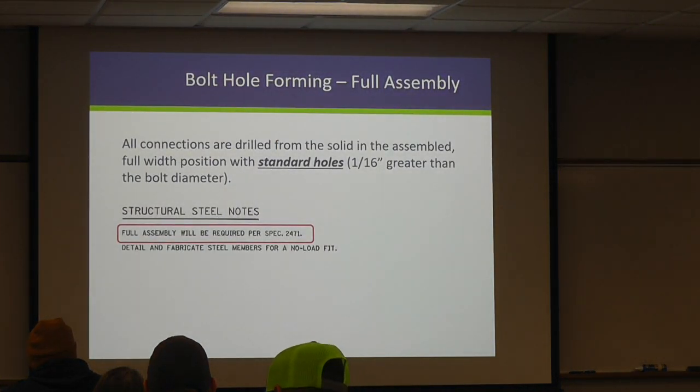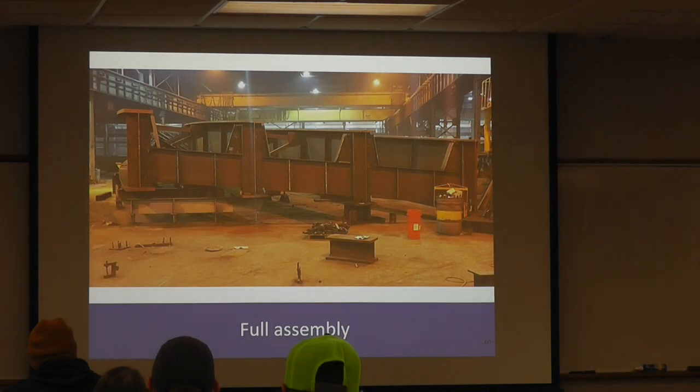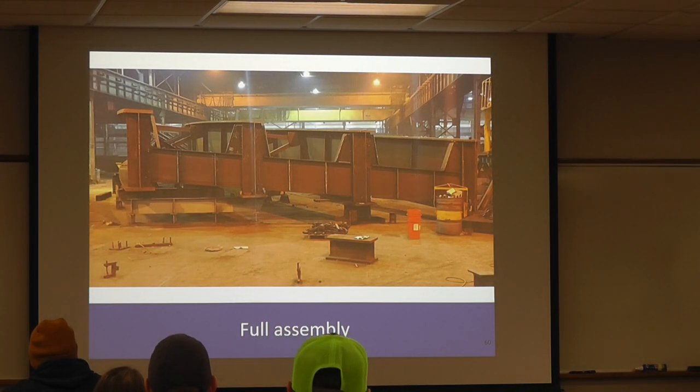Then we have full assembly, and this is where all of your holes are going to be subject to a standard size, not just the field splice. So this includes the diaphragms. What does that mean? That means the contractor has to set up the bridge before they start their hole forming operation.